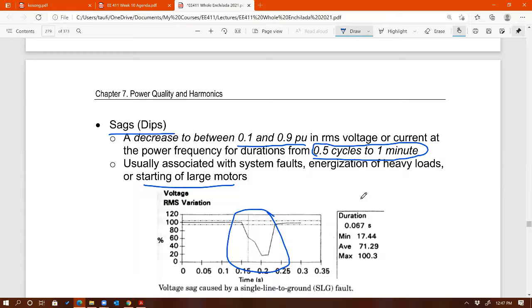Doesn't the rotor need to be spinning in an induction motor to cause the back EMF to work? So it basically is stalled at low speed. It has no starting torque. Very good. Yes. So flux has to be generated first. And when you start an induction motor, the rotor is still not moving, and so you're still generating flux within the air gap.